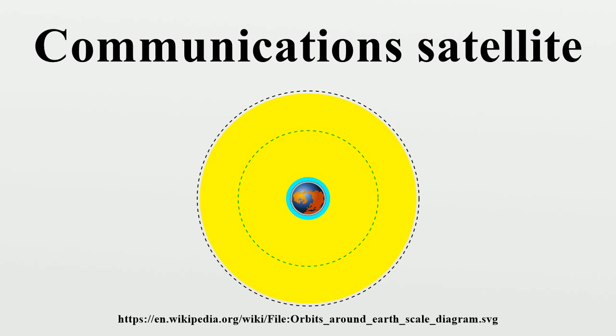The Molniya orbit is highly inclined, guaranteeing good elevation over selected positions during the northern portion of the orbit. The Molniya orbit is designed so that the satellite spends the great majority of its time over the far northern latitudes, during which its ground footprint moves only slightly. Its period is 1/2 day, so that the satellite is available for operation over the targeted region for 6 to 9 hours every second revolution. In this way, a constellation of 3 Molniya satellites can provide uninterrupted coverage.